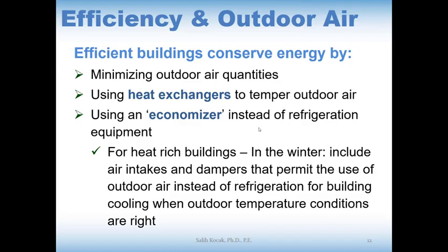That's why economizers describe the air intakes and dampers that permit the use of outdoor air instead of refrigeration for building cooling when the outdoor temperature conditions are right. Even better are enthalpy controlled economizers, which are available nowadays.